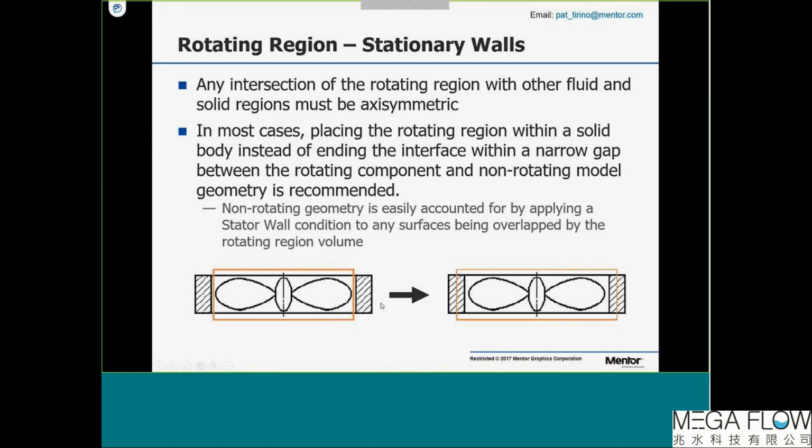And that means 8 cells in the entire height and in the entire 360. And that may not be economical. That may lead to 10 million cells just in this area. And it's a lot more than we need to put here, okay? So to avoid that 8 cell minimum, let's say, we can do this.